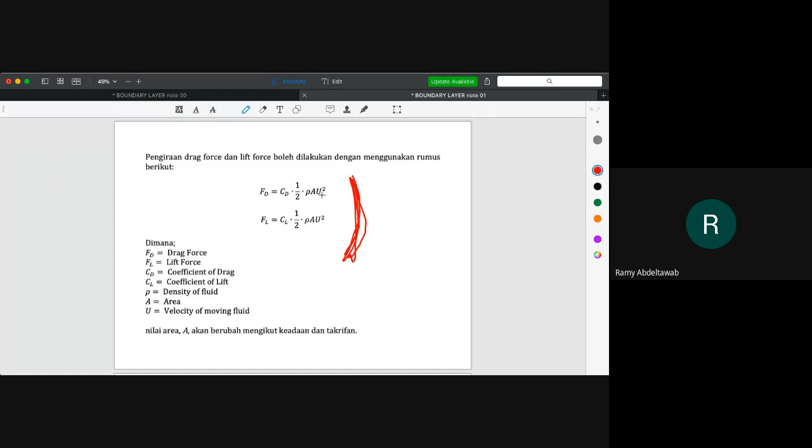However... Professor, I have a question. Can I ask a question? Okay. For the area inside the drag force equation, is it for the surface or the thickness? For the surface. Because, for example, we have a plate here. The fluid flows, the molecules will travel from here to here, so you need to calculate all the area here, which means the length times the width. Okay, can you get it? Yes, I got it. Thank you.